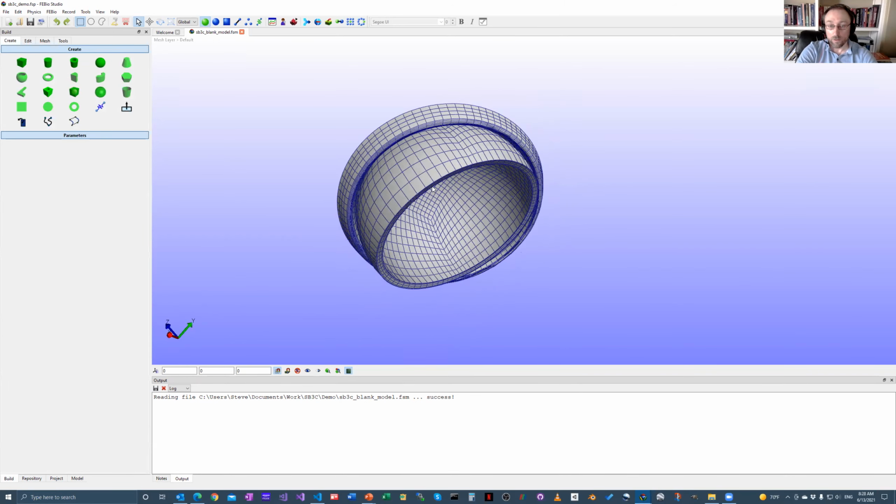If you click on the pelvic cartilage and then click on the H button, it will hide that part, which gives us a clear view of the femoral cartilage. Okay, so let's add a material. There's a couple of different ways we can do this. We can go to the materials item here, right click and say add material, or we can go to physics, add material.